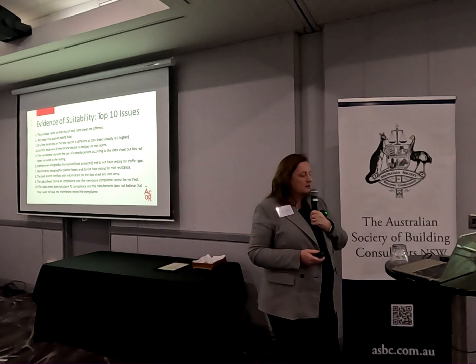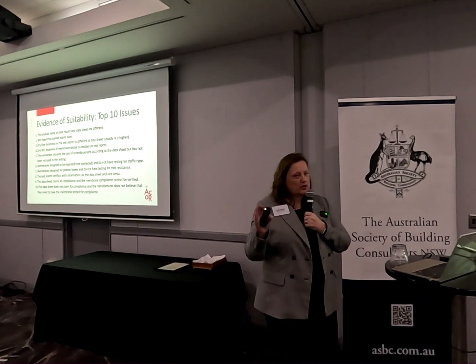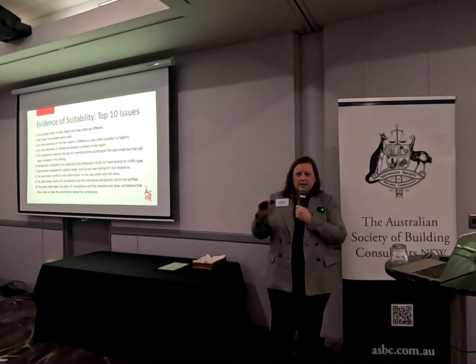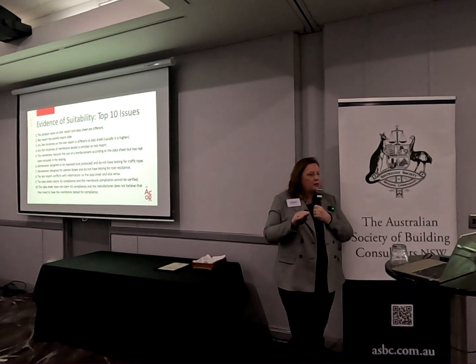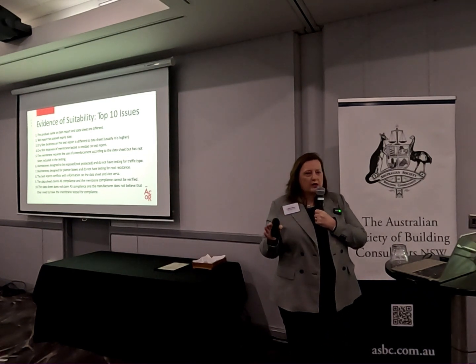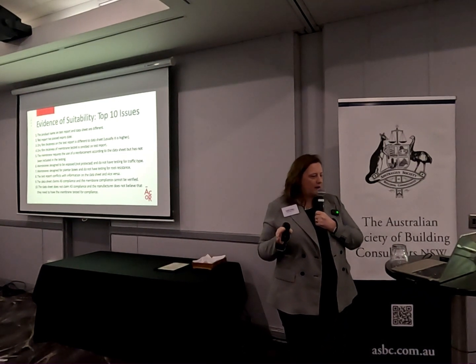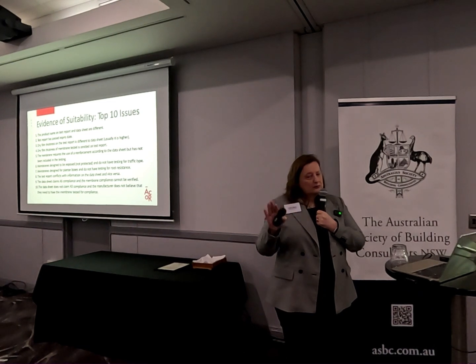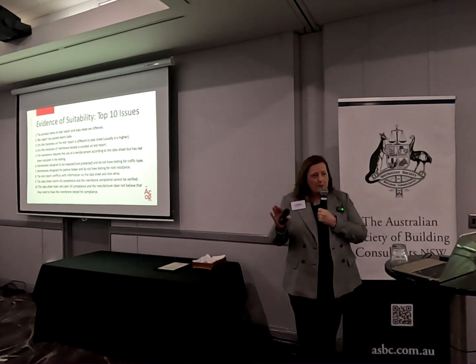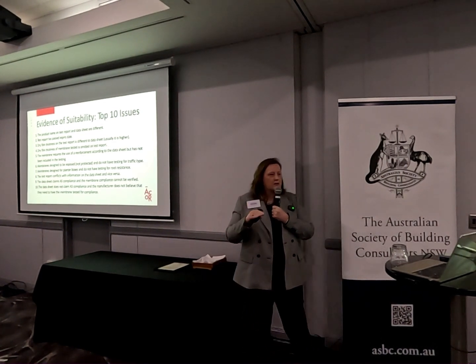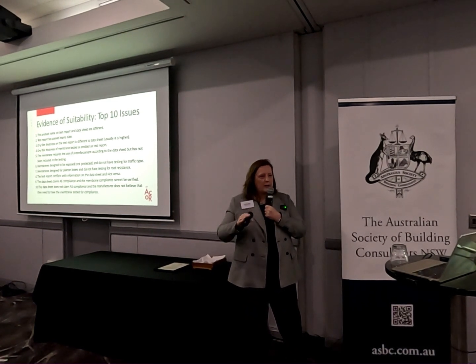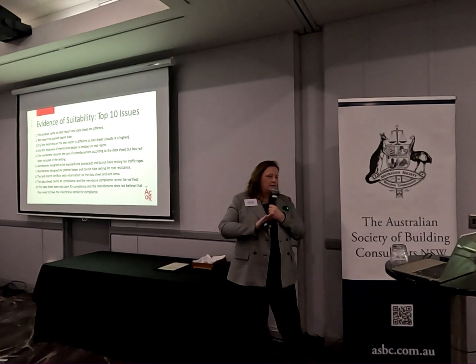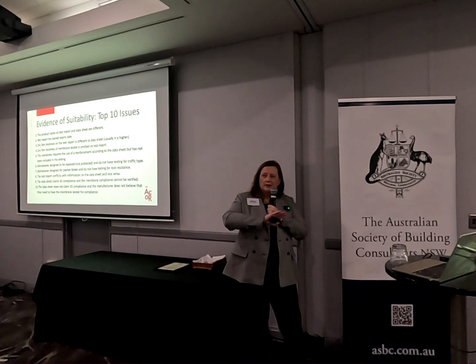So dry film thickness, especially for a liquid membrane, because with a sheet membrane, it is something that is fixed in the factory. It's made to a certain tolerance. But the liquid applied, and let's face it, that is a majority of what gets applied out there, some, not all, suppliers might put a lower film thickness on their data sheet so that when someone goes to calculate the applied costs and compare products, theirs will look pretty good because they don't need as much material.